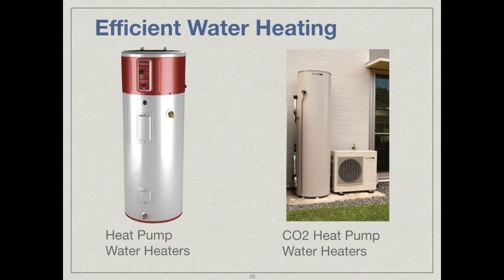If you didn't want to chill the space that the heat pump water heater is in, and you didn't have a basement or a garage, that kind of buffered space, you might want to think about a heat pump water heater that uses an outdoor unit. These units are called CO2 heat pump water heaters. They're fairly new in the market. The tank goes inside, but the unit is outside, so it doesn't really cool the space that it's in.